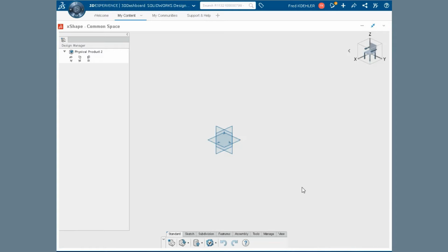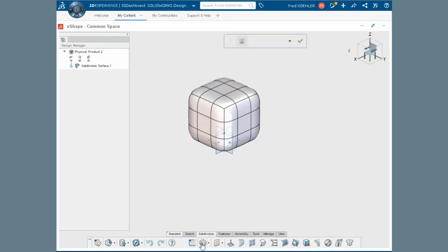This time we'll use a different yet common primitive sub-D surface type, a box, to create a remote control type of model. It will be added using all of the defaults. I just click the box primitive icon and press the Enter key. It appears at the origin location.